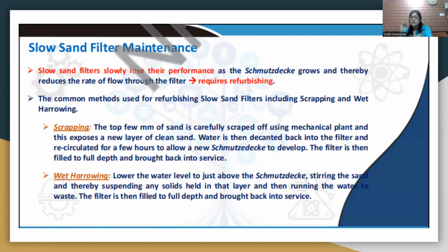So if you have a thickness of the sand material, which is one of the filter materials, after a while, because of the accumulation of impurities on it, it is going to be inefficient. So in order to maintain the efficiency of slow sand filters, the top layer of the sand filter material is removed, so that the bottom material, which is relatively cleaner, is exposed.